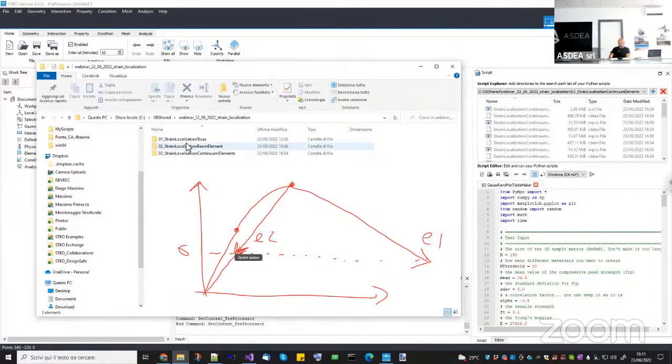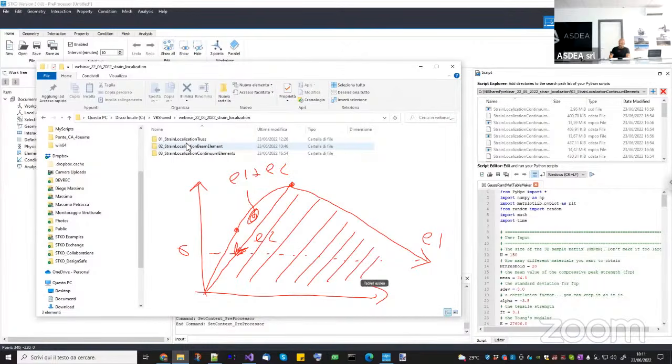What happens is that now we have this first area, that is the energy dissipated by both elements, okay? Element 1 plus element 2. But all this area here instead is an energy dissipated only by one element, only by one finite element. This one will give problems, okay? I will show you through some examples why the concept of having this energy that is dissipated only by one element can give a lot of issues, okay?